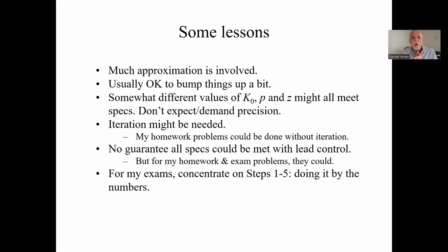Anyway, some lessons of all that, of all this using the Bode plot. There's a lot of approximation involved. Don't expect precision. It's usually okay to round things off, but if you round them off, round them up. Somewhat different values can still meet your specs. This is not a case of precision. You might need to iterate.